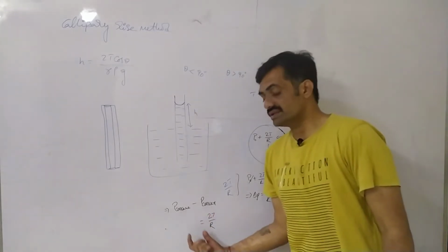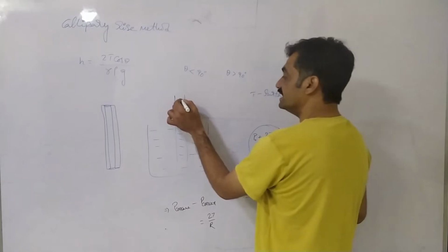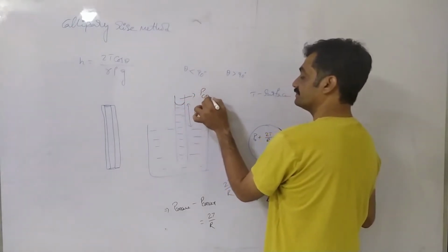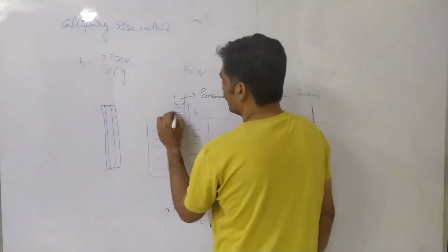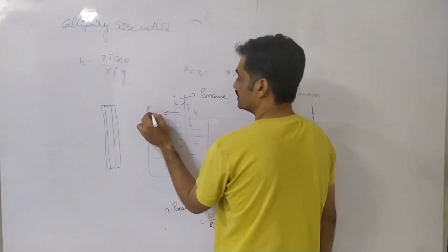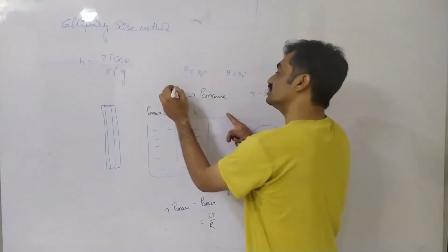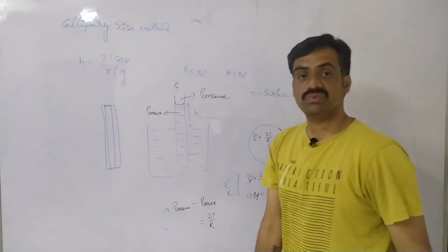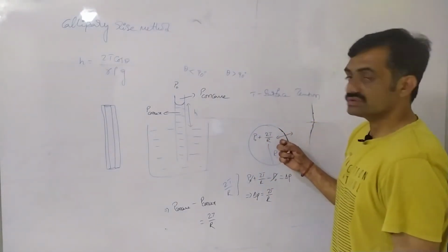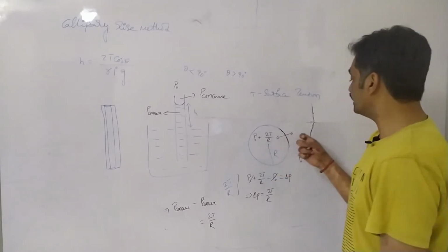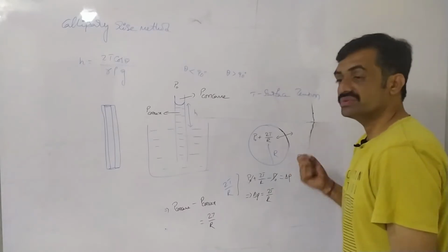Now when we compare this equation, observe that here we got a meniscus. It has a concave side and a convex side. The pressure on the concave side is due to the atmosphere, so we represent it as P naught. On the convex side, the pressure P is acting.